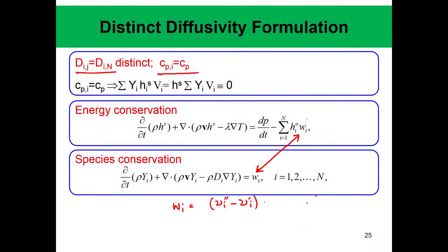And then you have the k term, that is, k is a reaction rate constant times the continued product, j equal to 1 to n, Cj to the power nu j dashed, and then k is nothing but b times T to the power of alpha, exponential of minus Ea by R0 T, right. So, you see that in the species equation, this is the omega i form, and this k contains the temperature dependence.